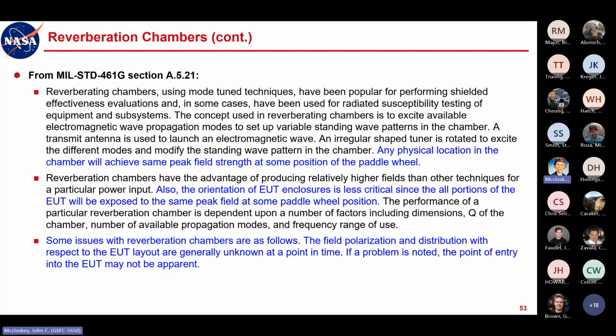So I can localize what the problem is with a test like CS114. With radiated susceptibility testing, the nature of a susceptibility is going to tell you that the susceptible circuit is where your susceptibility is manifesting itself, but you still may not know exactly how the energy is getting in to corrupt the circuit in question.